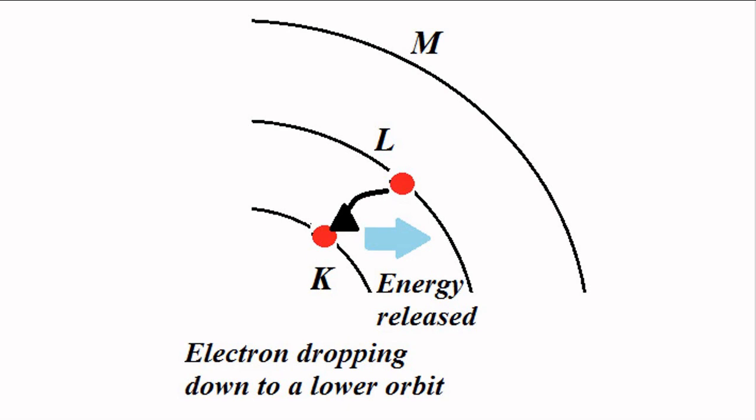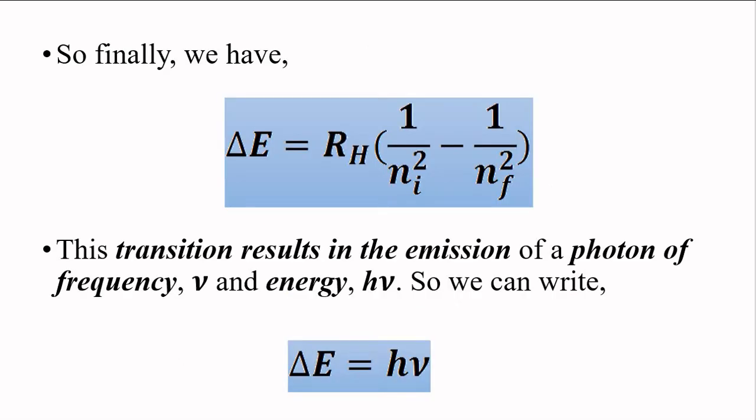Because of these transitions, it is very important when we discuss the design of optoelectronic sources and optoelectronic detectors, because in optoelectronics light is the main component. So here the absorption and emission of photons of particular frequency or wavelength come into play in relation to the atomic structure of semiconductors.